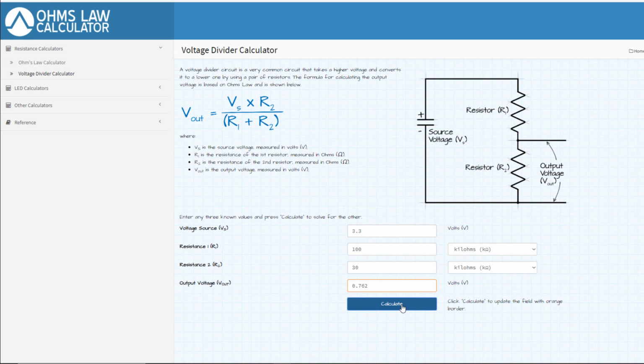So I get an output voltage of approximately 0.7 volts, and I found the resistance of the LDR at zero light to be approximately 1 mega ohm. That approximately comes to about 3 volts.